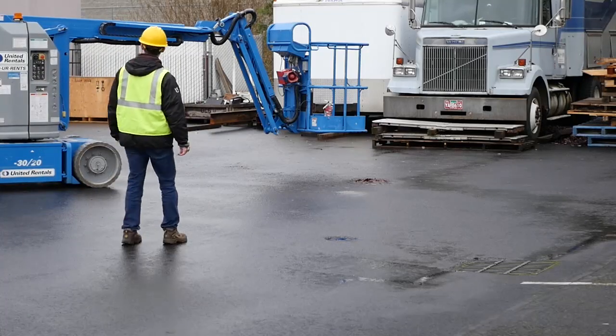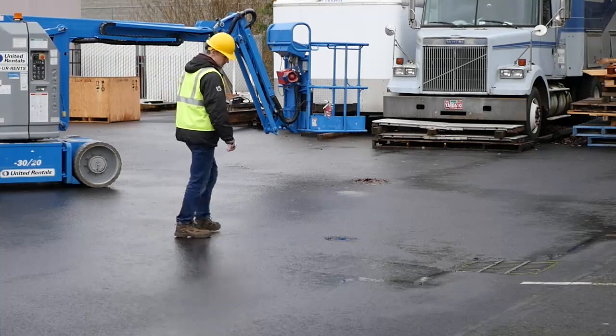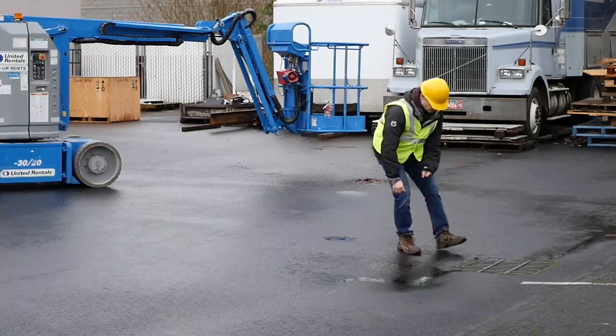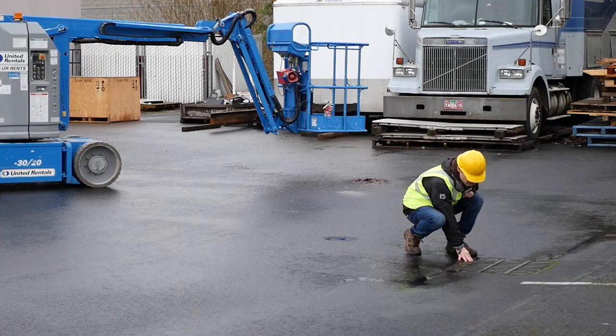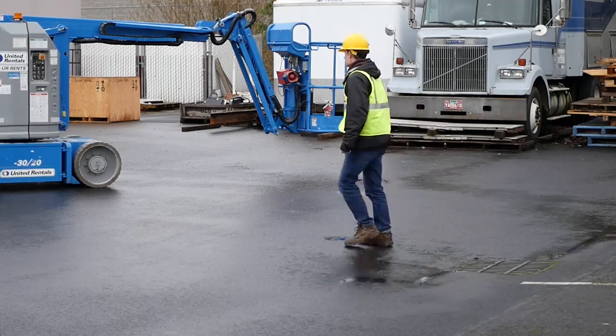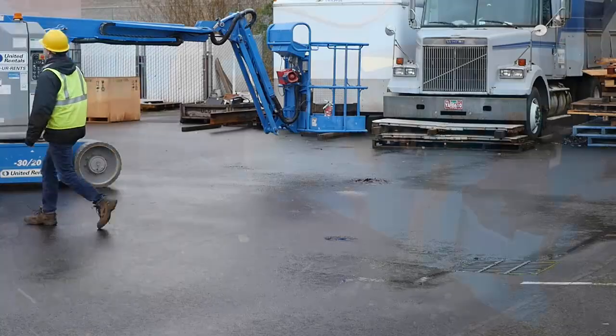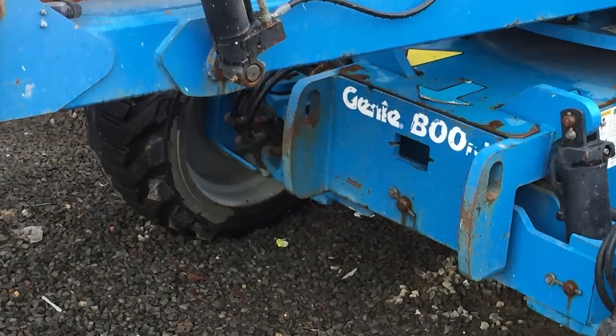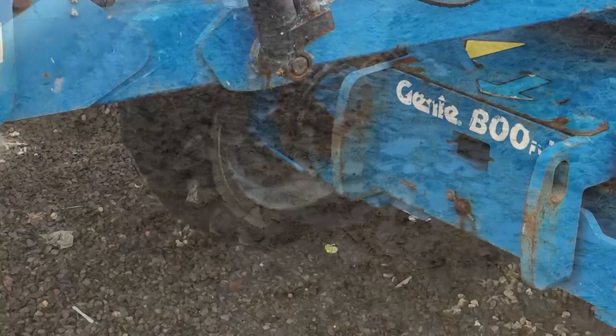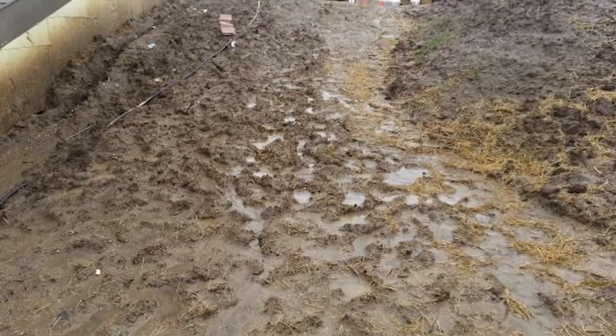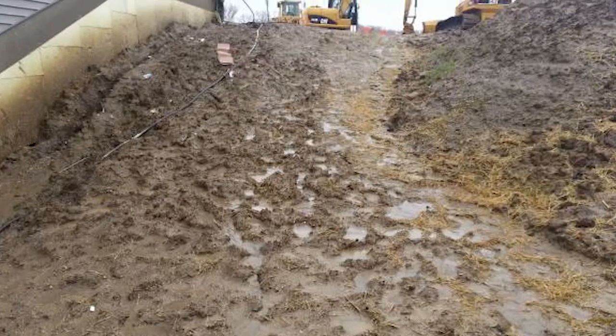It is important to inspect the work area before using an aerial device. Most accidents that occur are a result of a hazard that could have been identified if the area had been thoroughly inspected. Make sure the ground is strong enough to support the vehicle. Soft dirt or other surfaces may not be able to support the weight and may cause the vehicle to tip.